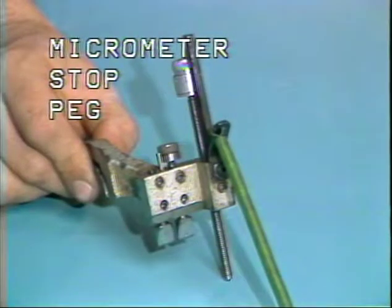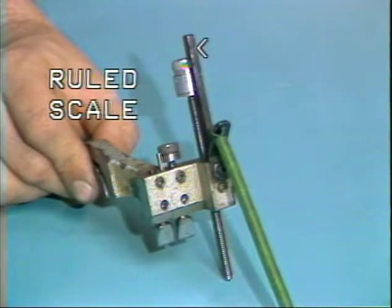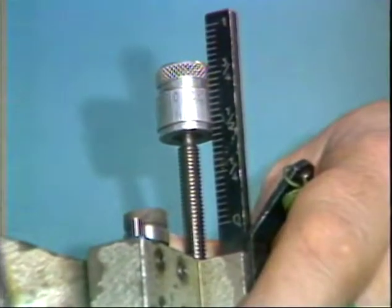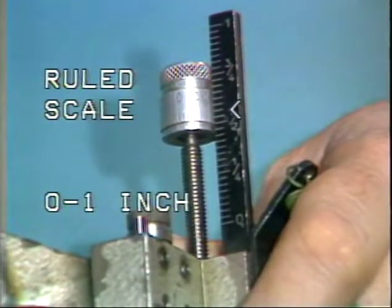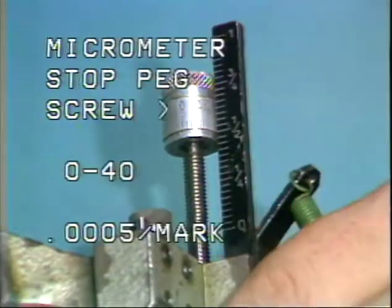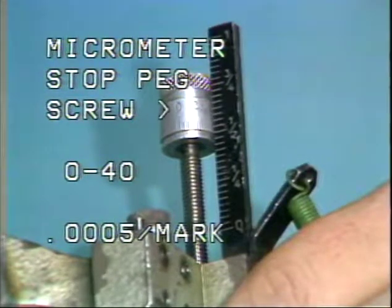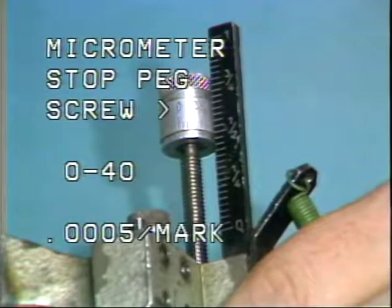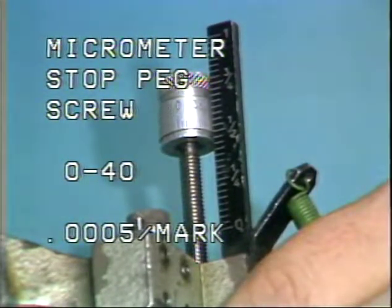This is the micrometer stop peg used on the 2-to-1 ratio attachment. The purpose of the stop peg is to adjust the length of the machined part. Located next to the stop peg is this ruled scale. The purpose of the ruled scale is to indicate the feed length setting. The ruled scale is marked 0 to 1 inch. The stop peg is also marked. The markings are 0 to 40. Each line represents 1/2 thousandths change.